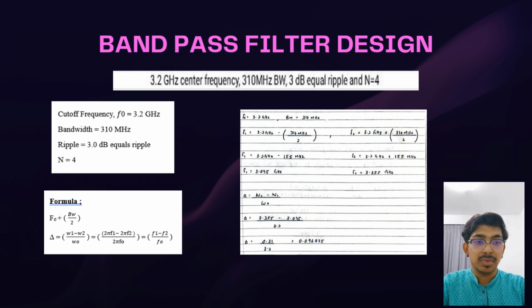The insertion loss method is used throughout the design process. This method enables us to determine the filter order required to satisfy the design specification and then calculate the corresponding inductance and capacitance values for each resonant section.